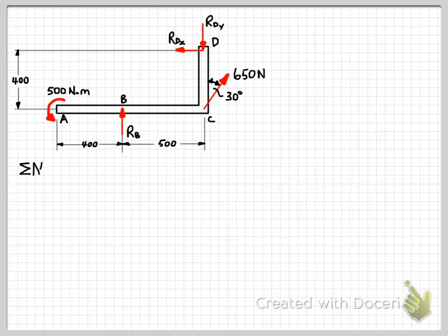So the moment equation that we write, of course, will be sum of the moments about point D, anti-clockwise positive, all equal to zero. Okay, so it's very important that when you write this equation that you have this indication here for where you're taking moments about. You must indicate the location for calculating the moments, so that you and anybody else, when they come to check your work, can see whether the equation that you've written is correct based on this indication here. Otherwise, they've just got to try and guess. And if you've got to guess, well, then you haven't done it well enough.